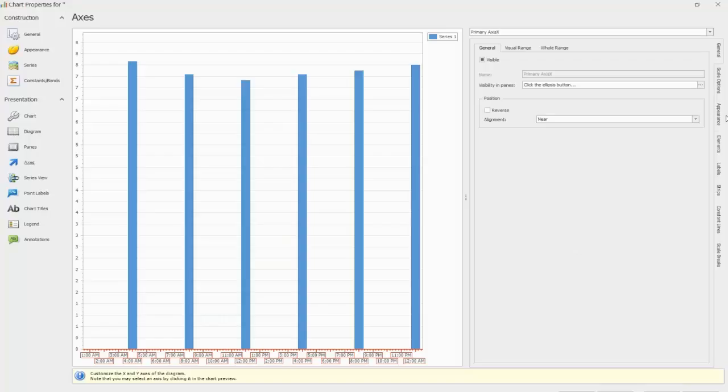By selecting our axis, it's going to bring up a list of options here to our right, and we're going to have several tabs we can work inside of our properties window to modify our options for our X and Y axis. For example, you'll notice the way that it has the scale breaks inside our current bar graph, that it's creating duplicate values at each of those scale breaks, because it's looking at our data and seeing that the maximum range for my data is 8 and the minimum range is around 0.